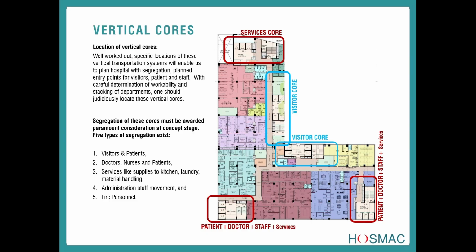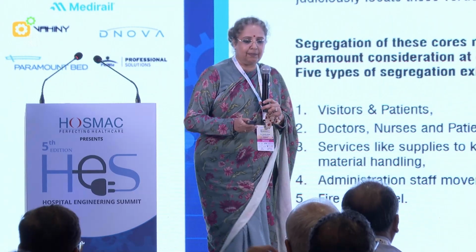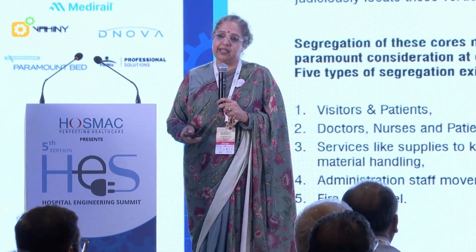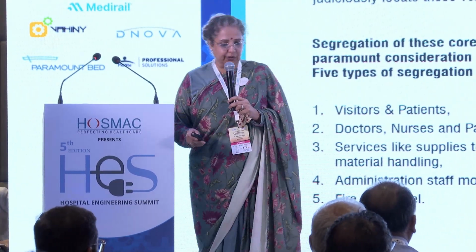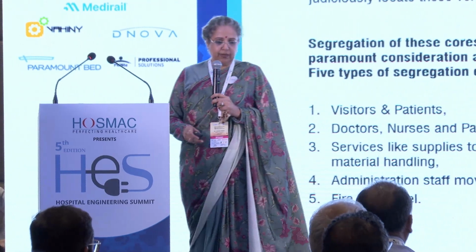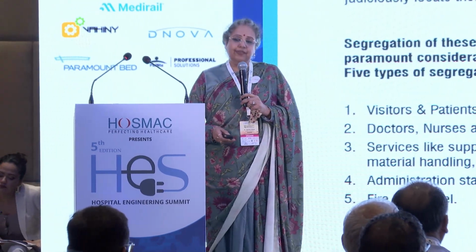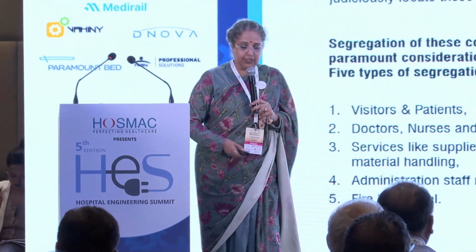So for patients and visitors, segregation; doctors, nurses, and patients can be combined together. Services like supplies to kitchen, laundry, material handling need to be separated out in another vertical core. Administration staff movement, and fire personnel, of course, the fire lift I had spoken about earlier.